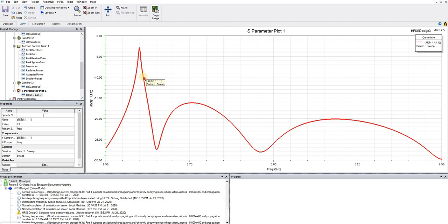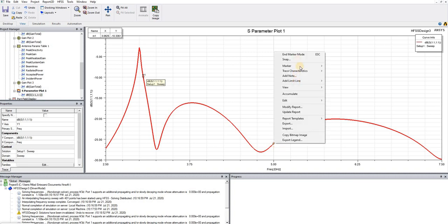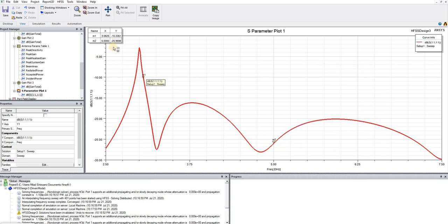Because it's a high gain and wideband antenna, it's used as a reference antenna and a standard reference antenna for measuring other high gain and pattern antennas. As you can see, from about 3 gigahertz to about 10 gigahertz, this antenna works and radiates power, and at 5 gigahertz it's minus 25 dB, almost minus 26 dB for S11, and all the power radiates to free space.